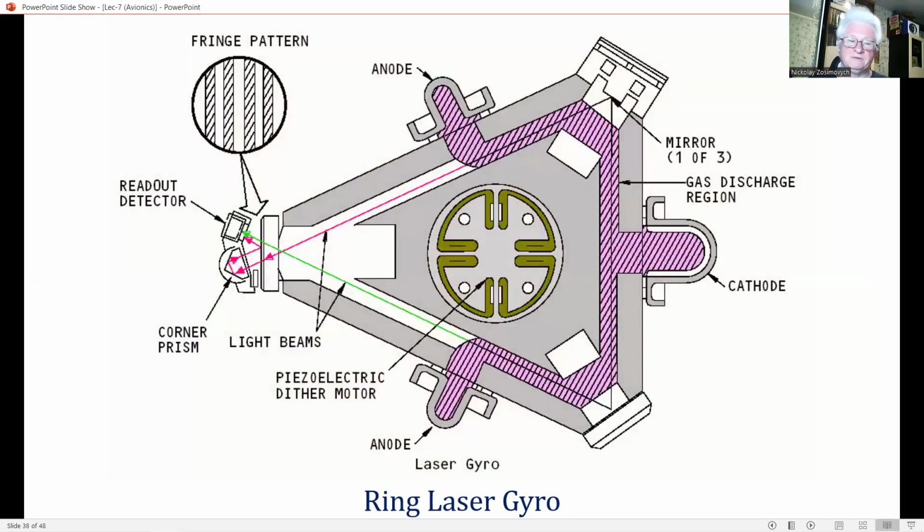At the lower end of the accuracy spectrum, micro-machined vibrating mass rate gyros exploiting semiconductor manufacturing technology have become well established. Avionic applications include flight control and solid-state standby artificial horizon. They are extremely reliable and rugged devices with low power consumption and offer the major advantage of relatively low cost.